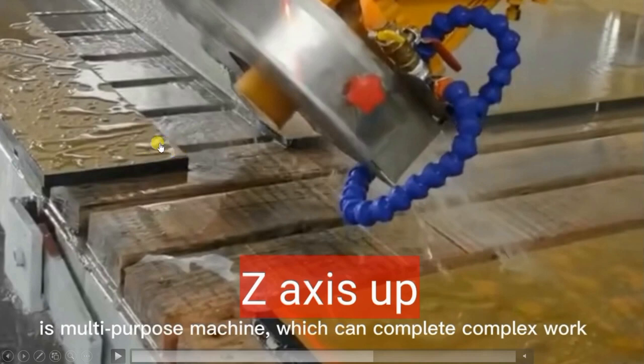By the pulses coming from encoder, we will count the pulses by high speed counter. Then we will do comparison of the counter value. If the required distance is achieved, that means if the required count pulses are achieved, based on that, we will give reverse and forward commands to our servo drives. So this is how the programming works.